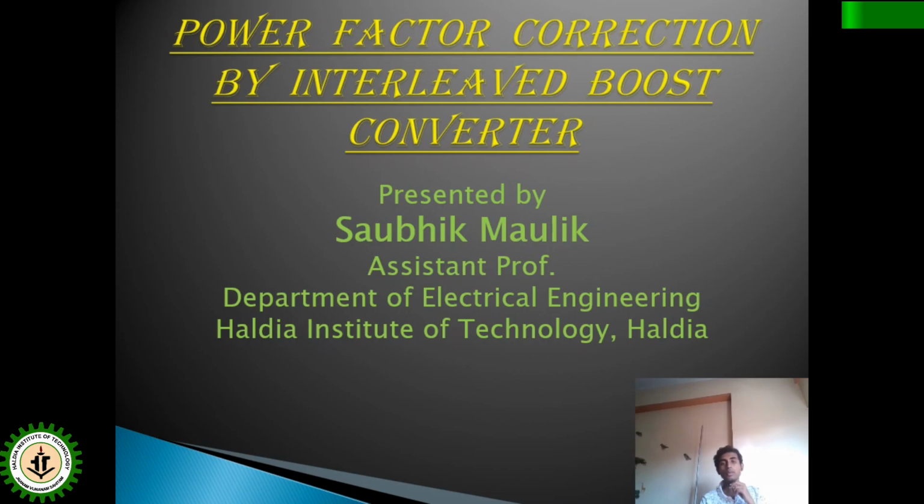Now to make that rectified DC voltage constant, we use capacitive filters. The introduction of the capacitor distorts the input current because the current drawn will be in the form of spikes, and the power factor as well as the THD gets deteriorated.